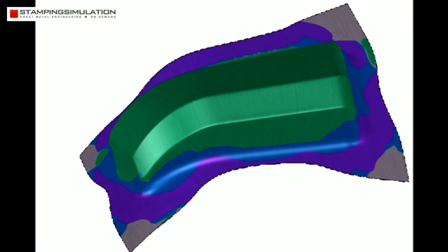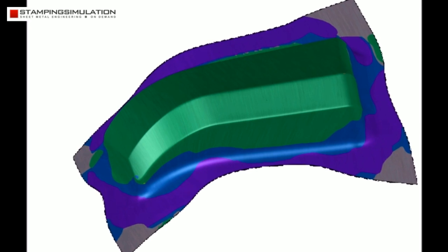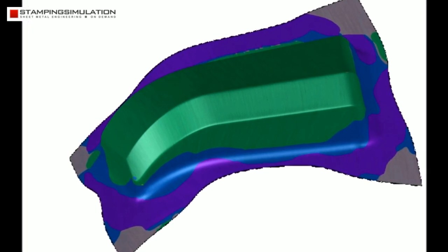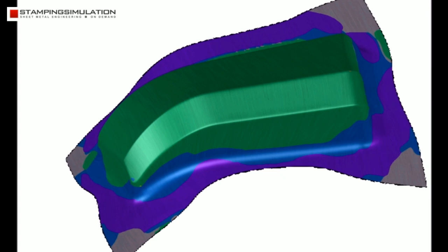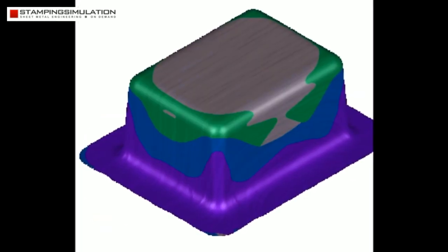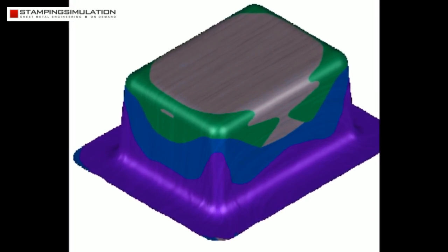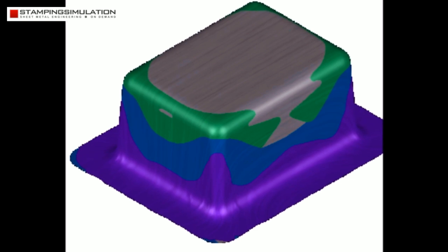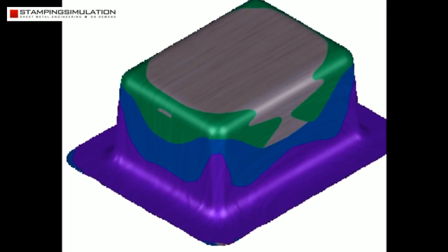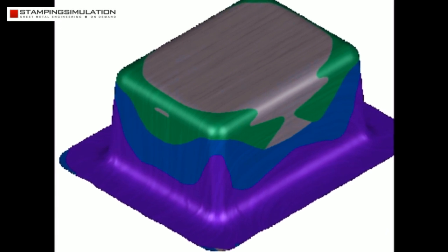The mechanical properties of the sheet metal material being simulated are of extreme importance, and are used in the simulation directly. The stress and strain are calculated at a finite number of points on the sheet using the finite element method. Stamping simulation uses AutoForm incremental sheet metal forming simulation software to perform advanced simulation analysis for all sheet metal forming processes, and considers the 5 most important parameters to be as follows.